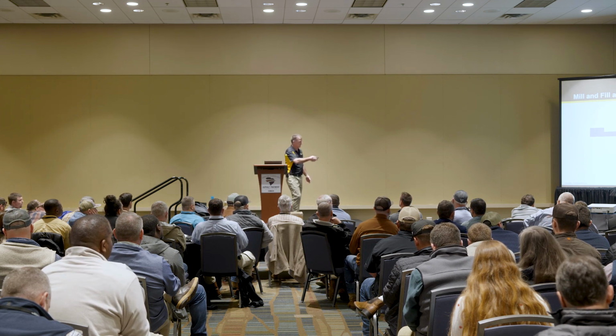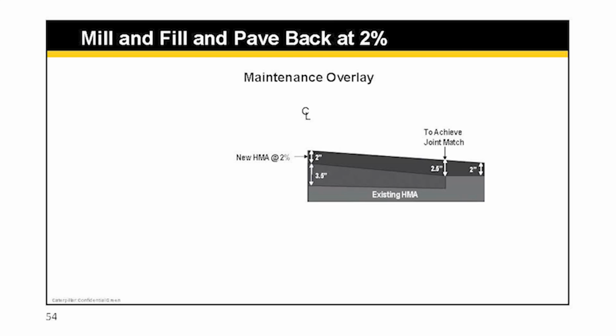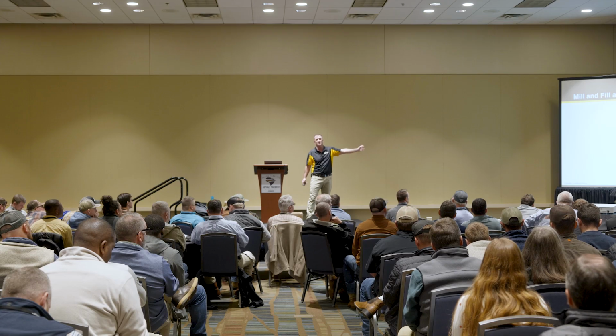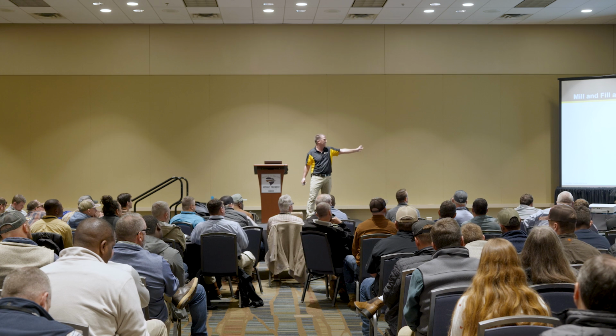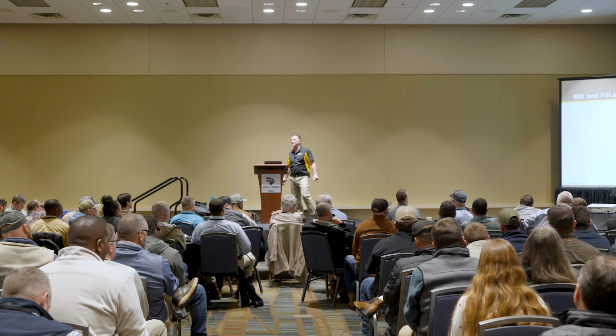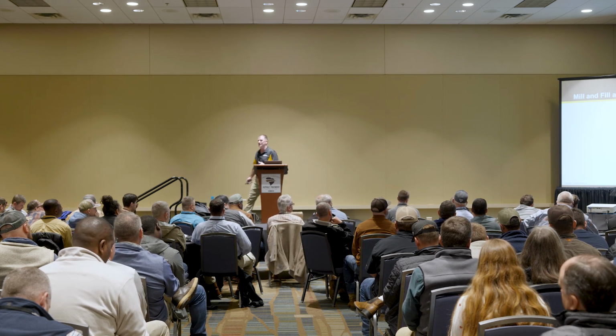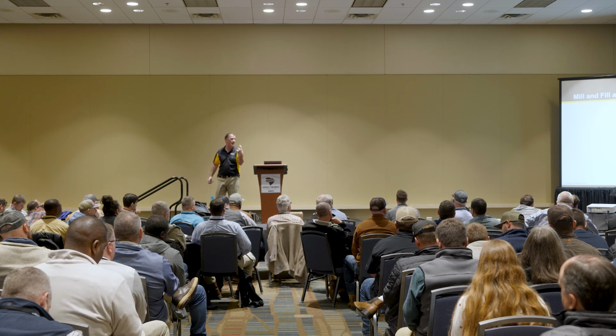It's everybody involved when it comes to planning this stuff. And there's your overlay. So this again, another way of doing it. I mean, it's going to be really thick there, right? Because they had a partial paved shoulder. They didn't mill out the shoulder, they only milled out the main line. Now you're like 3.5 inches to match that shoulder at 2%. Come back, put your top lift in.